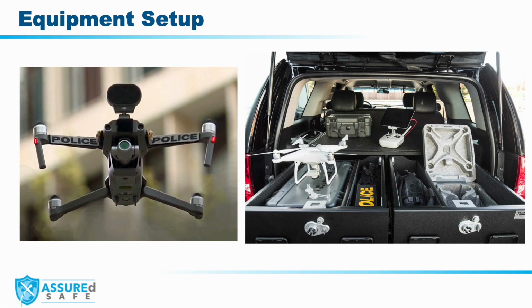Make sure that you develop a flow for setup and teardown. This should be operationalized within your standard operating procedures. One process may suit your operational capability, or you may require variations to support long or short-duration missions. For instance, for a quick flight, you probably wouldn't deploy a tent or canopy, but that shade may be valuable for reducing pilot fatigue on an all-day mission.